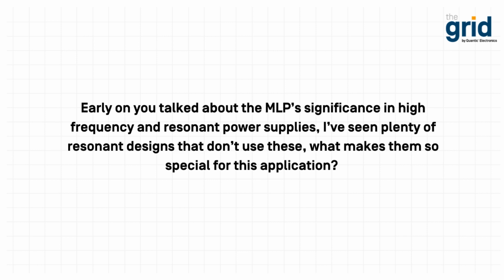But there's restrictions here. Again, our company in general is focused on high reliability. If your customer is looking for something that can operate over 85 degrees C, or if they are space restricted, the MLP provides the best choice. If you're looking strictly at wound capacitors for this application, they can often be used as long as that temperature rating is met.